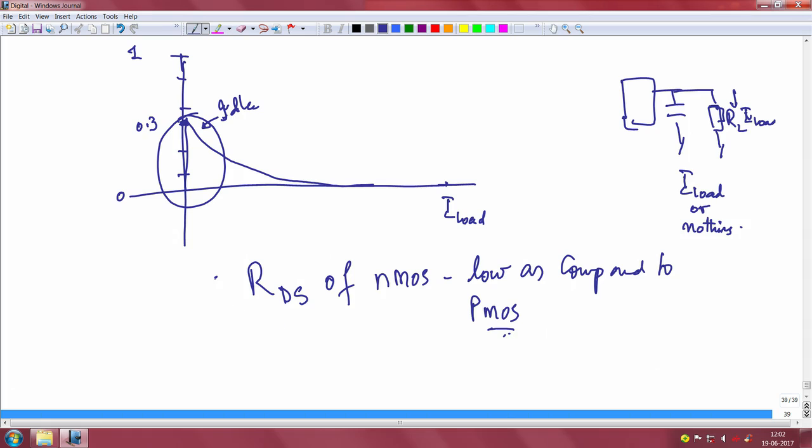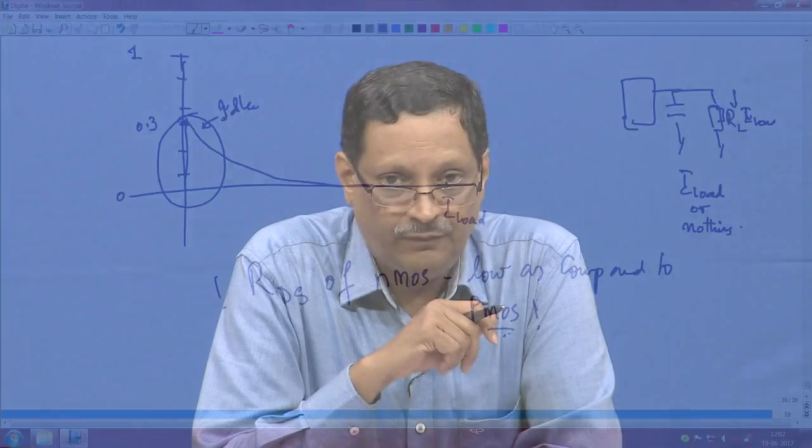So this is what we said, it is always a good idea to actually sketch the circuit diagram of a PMOS series pass element as well. So let us do that, so that we understand exactly how both the circuits really work, because in the NMOS case you needed a charge pump to ensure that the gate control is there, because the gate voltage has to be higher than the output voltage. And the only way you can do that is to introduce a charge pump.